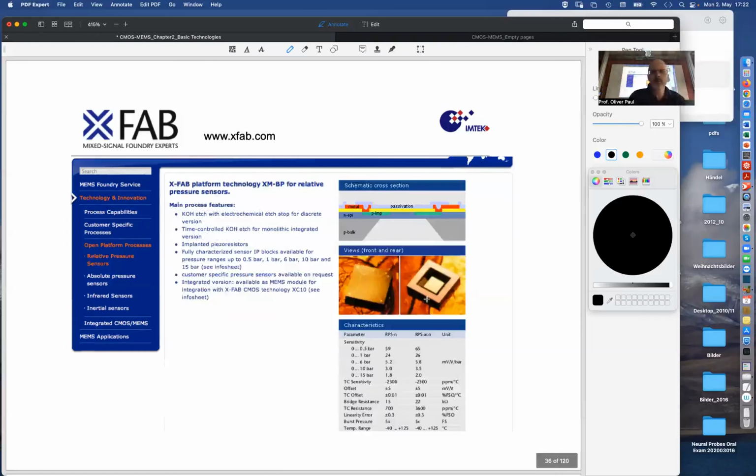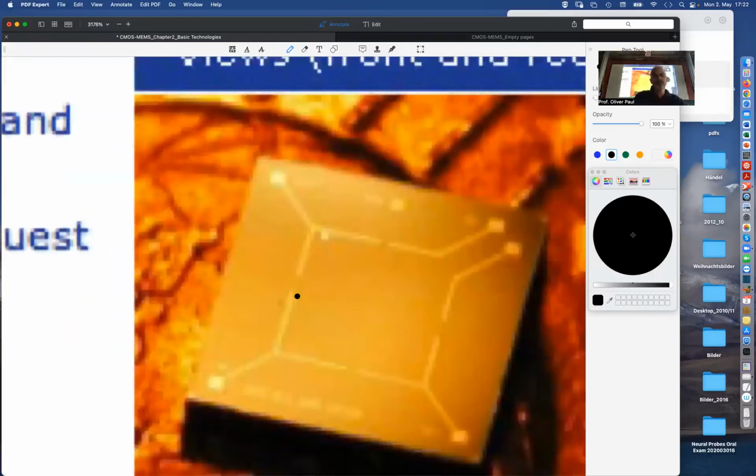If we look at here, we have an outcome of visibly a pressure sensor. I have no doubt that this is a pressure sensor, where we see this micro machining from the back of the chip, leaving a silicon membrane, which is underneath here. And then there are contacts which contact probably diffusions. It's not so well resolved, but for sure there will be some diffused resistors in these areas that allow to measure the deformation of that pressure membrane when a pressure difference is exerted onto the pressure.